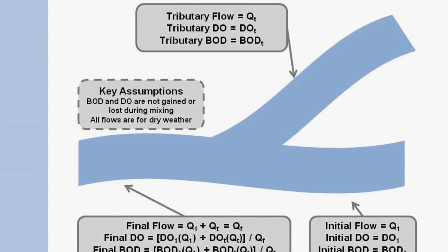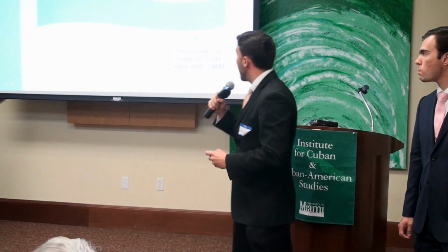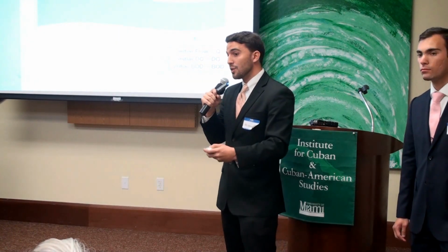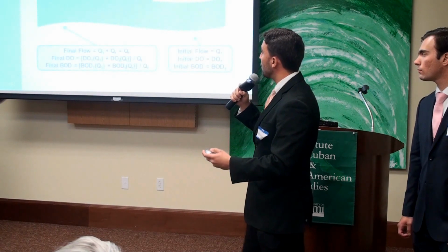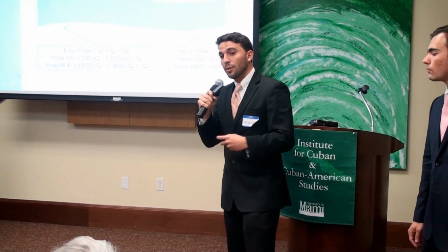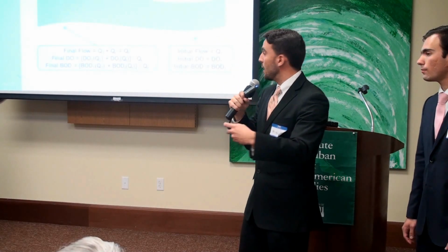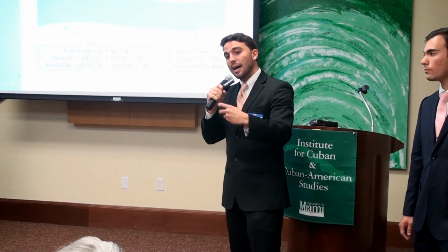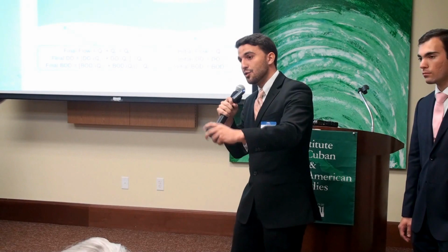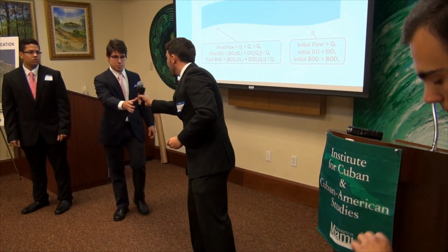The dissolved oxygen was modeled by using the initial base flows obtained from Eric's data and then inputting the inputs that we estimated from each point source. And later, using a weighted average, we were able to determine the relative biological, chemical demand and dissolved oxygen concentration downstream of the river. Using the dissolved oxygen concentration values obtained, then we are able to model the relative water quality downstream of the point sources. And now Sergio will speak about the final results.